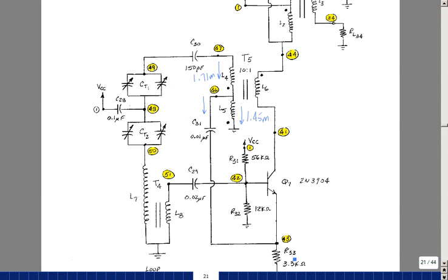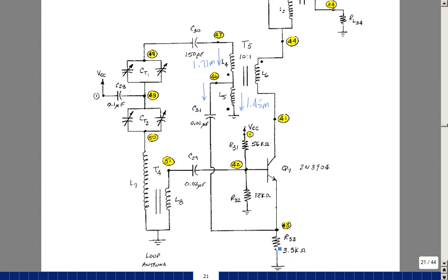Now, if you look at the transistor current, it's equal to 0. The reason for that is a couple of things. One is the current that flowed down in here created a drop across this resistor a little bit higher than the voltage needed to turn this junction on. We're estimating that this node voltage would be around 0.88 when we bias this transistor on. That current is actually lifting this point up just slightly, enough to turn off this transistor. Because when current is coming out of these dots, then current will be coming into this dot on the transformer. So it wants to turn the transistor on, but that current is holding it off. So this part of the transformer isn't doing anything for that instant in time.